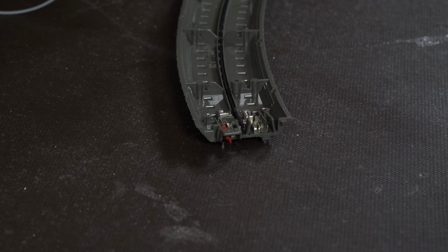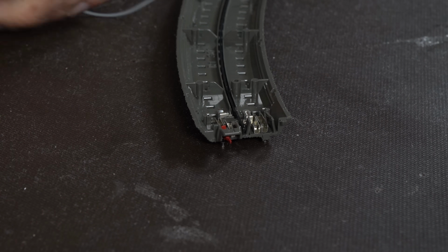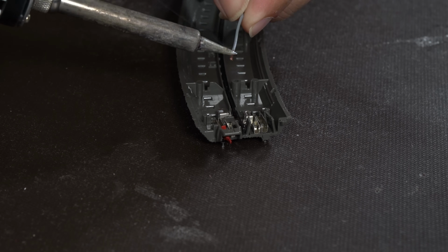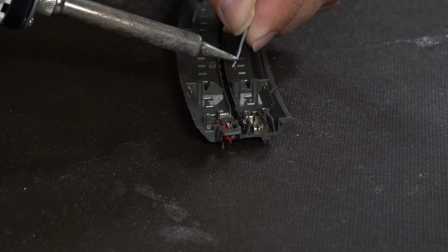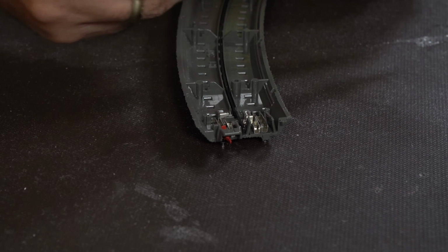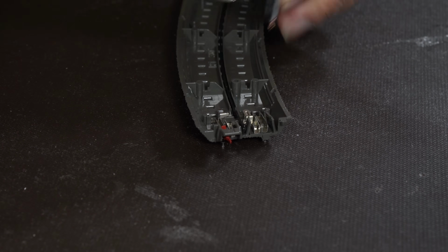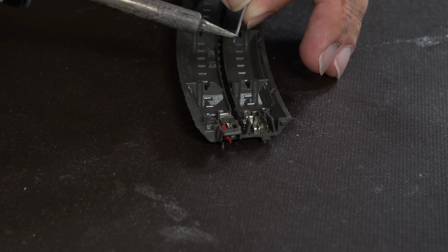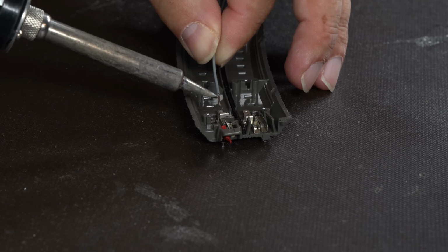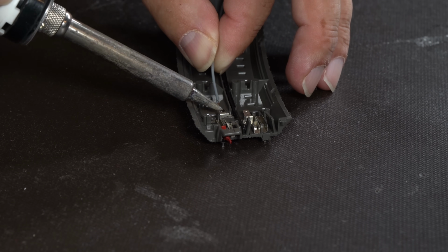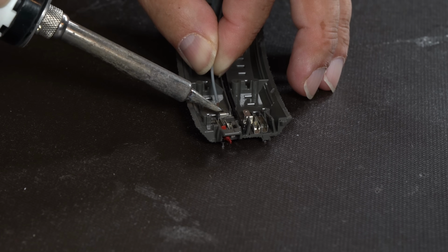I do the same with the cable, of course. That means I also lightly pre-tin the cable, which involves applying a small amount of solder to the strands before making the final connection. This helps the solder flow more easily and ensures a good bond. I use a bit more solder on the cable than I did on the other part, just to make sure all the strands are properly coated.